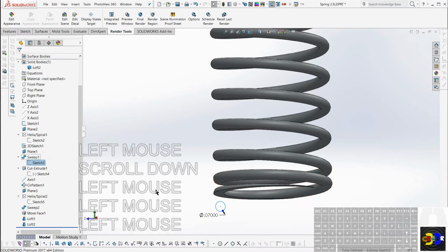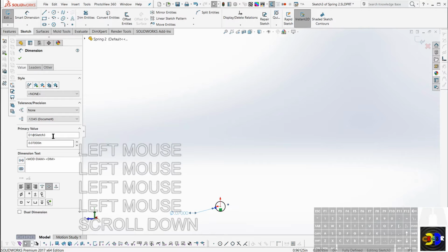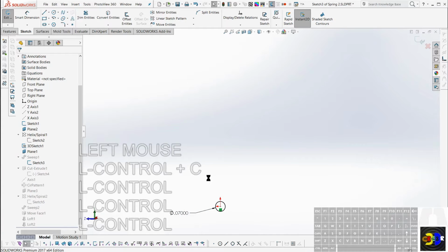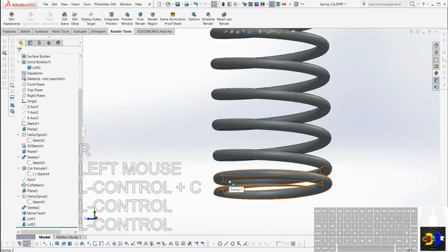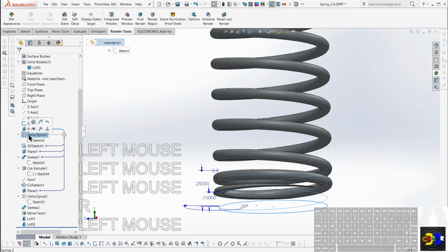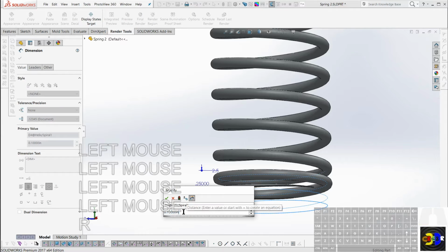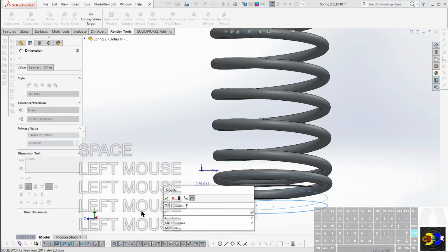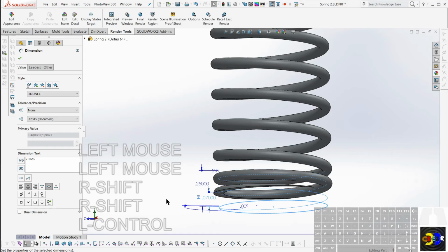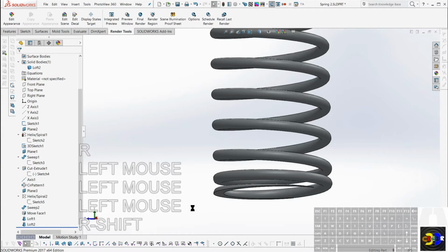Let's edit this sketch, so that way I can select this, copy this sketch, this dimension name, Control C, D1 at sketch 3. That way I can paste it into an equation here. So my helix here, double click this, and I will make this equal to quote, paste, quote, that. So now that will be an equation. You see this summation symbol.